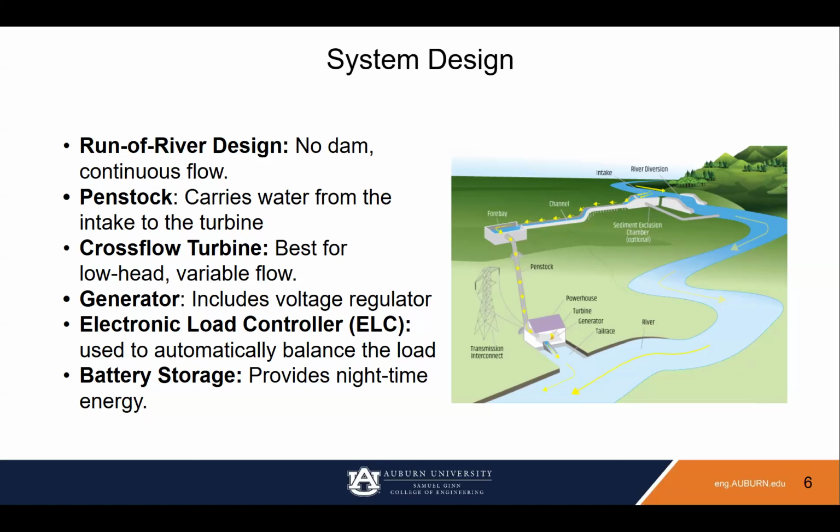And then as far as control systems, we would use an electronic load controller to automatically balance the load and prevent any frequency fluctuations or anything like that by diverting excess power to dummy loads. And of course, we would want to consider battery storage because you don't have the storage capability due to water storage of the large dams. Ideally, we would want to look at using LiPo batteries or something similar, but of course, you need to take into account that those are expensive and also not particularly great for the environment. So you need to be very particular about how you store them, make sure they're not at risk for exploding, catching fire, all of those lovely battery things.